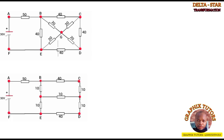Alright, so why am I doing this? If current starts flowing from the 5 ohm, from the point A, right, through to point B, it is split into I2 and I3. I2 and I3 flow through the 4 ohm resistors, continue flowing and reach this point C. There's nothing for it to split for, so it will now continue flowing through what?